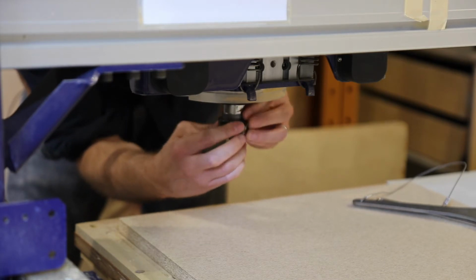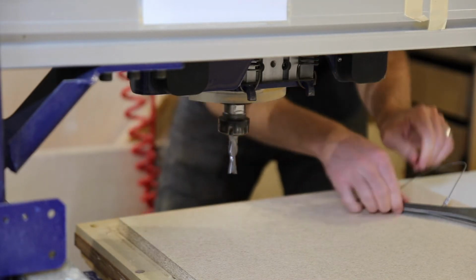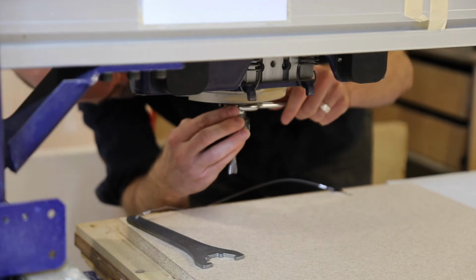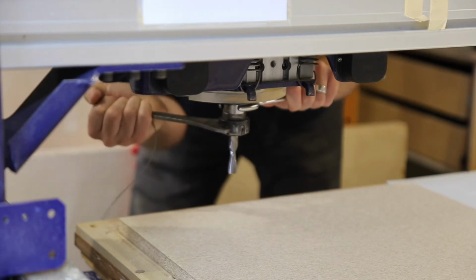You will need to enter the specific parameters of your bit when you generate your toolpaths in Aspire. Many bits have been resharpened and are now a smaller diameter. Check carefully with the digital calipers that the bit you are using has the right dimensions for your cut.